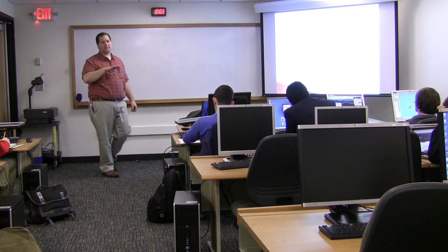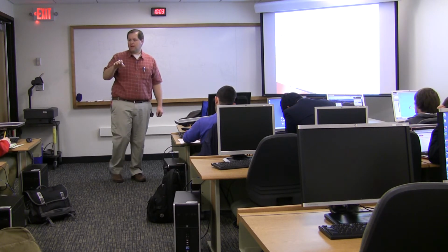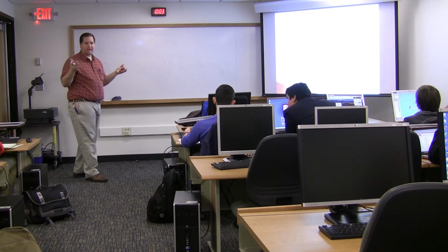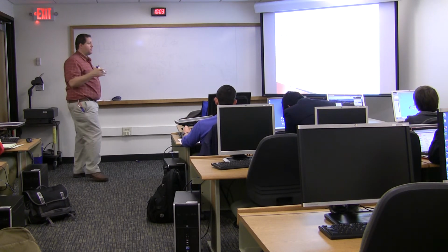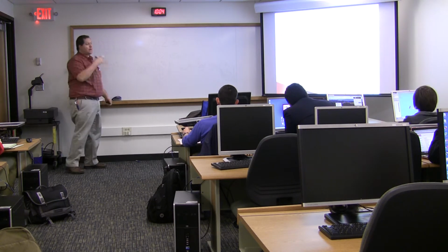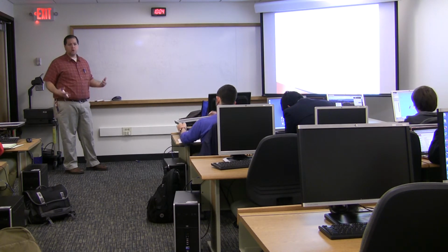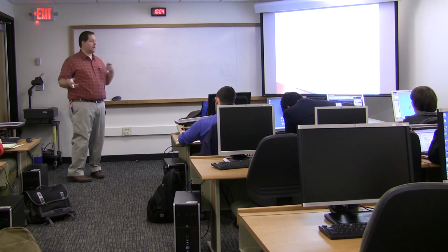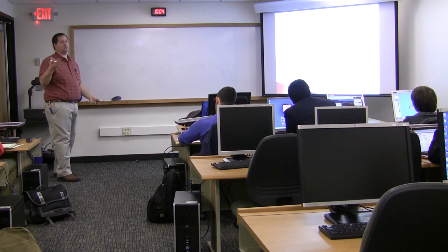So in our previous chapters, we've always plugged in omega and found the number, right? So you would have negative j5 or something like that for a capacitor. Now you have to leave the omega in as an unknown, and now solve for the output as a function of the input. So I can apply KVL, KCL, whatever tools I want. So if this is a simple loop, let me just do KVL.